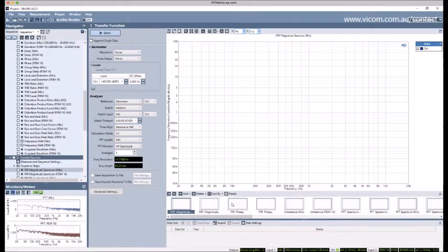The downside, particularly when we're measuring microphones that are going to be used in a voice application, is that very often the device may be doing some active signal processing and will have a non-linear response to a sine wave. In fact, to put it in short, many voice processing systems try to cancel sine waves. It's not human speech. It's not a desirable signal.